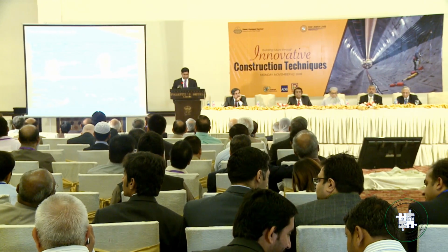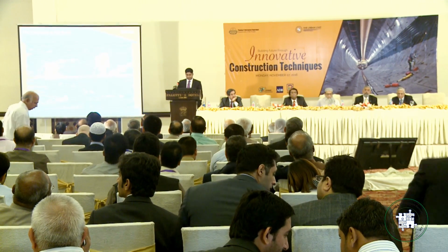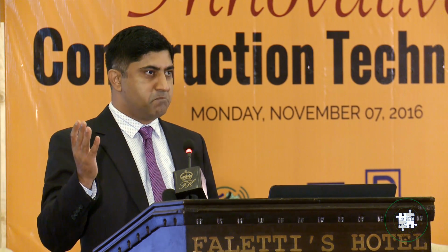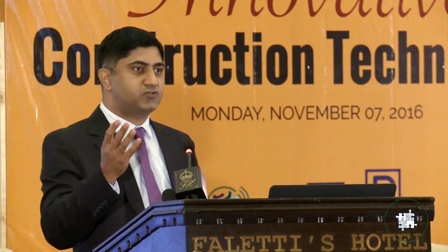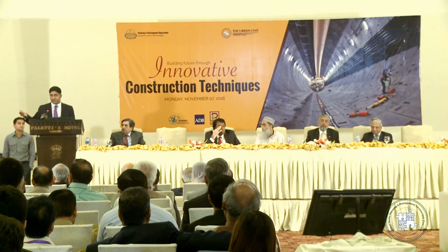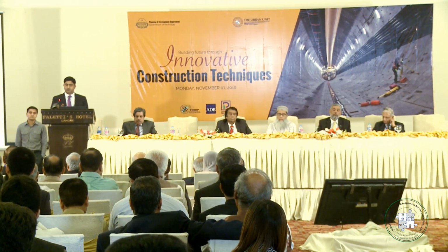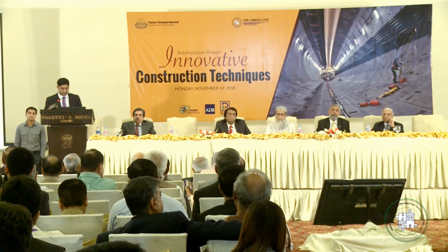With geo-grid, it was a different story. Only 2 men were needed, and it supported their weight. So that's the difference the geo-grid can make. It allows access to inaccessible areas. And then when we place the geo-grid, we can top it up with soil. We place another layer of geo-grid. You can run your lorries, you can run your trucks, and it offers you a competent foundation for the rest of the construction.